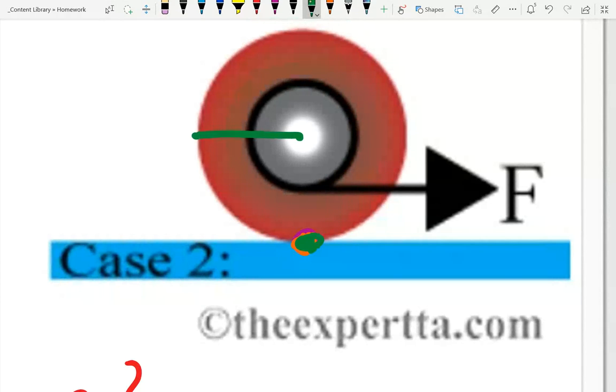We know this here is capital R, right? And what's the size of the orange line? Half r. So what does that leave this distance here to be? That's also another half r. Why is that the perpendicular distance? Because that is perpendicular to the force, going from the point where I'm summing the torque to where the force acts. It's got to be perpendicular to the line.